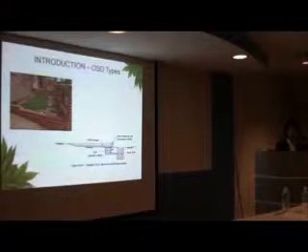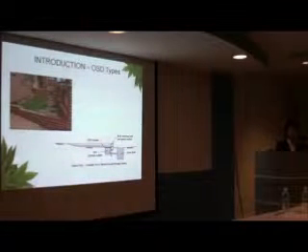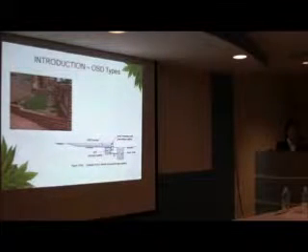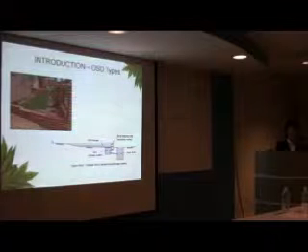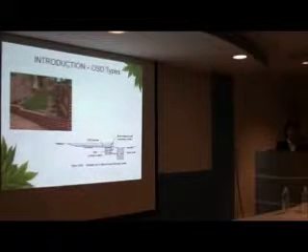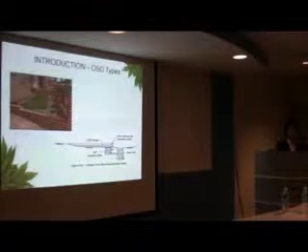This discharge control pit is actually a square or rectangular chamber, and there's a small orifice connecting this DCP to the roadside drain, and water will flow out from this small orifice to the roadside drain. The water will flow from the higher area to the lower area, and then into this DCP, through this orifice, and at the end to the roadside drain.